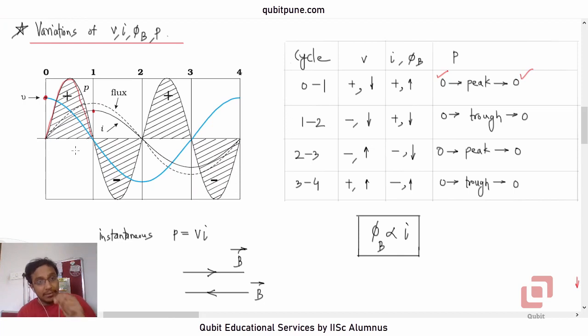Okay, so this basically refers to magnetization. This refers to the establishment of the magnetic field inside the inductor. Okay, now what will happen? The voltage has now reversed its polarity. So the voltage has become negative, so to speak. So this leads to demagnetization of the inductor. So the magnetic field inside the inductor is now going back to 0. Okay, it will go here.